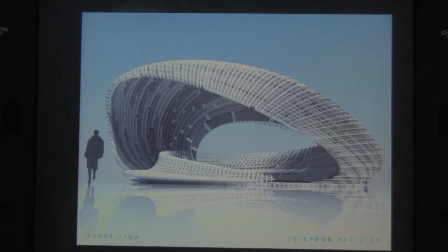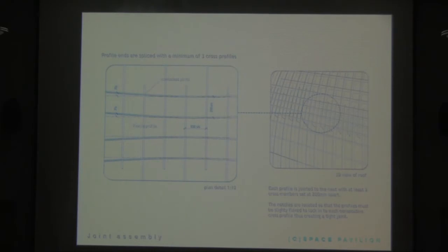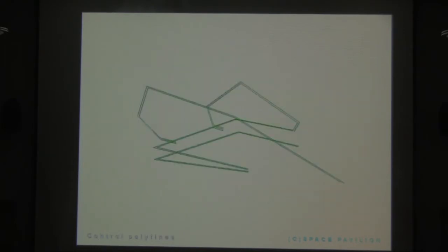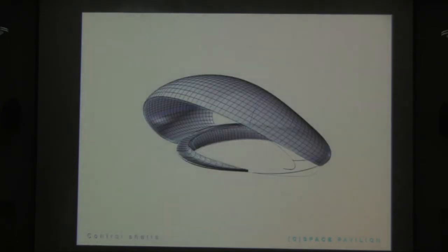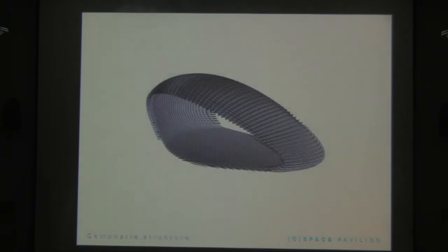So it's thin sheets of concrete with fiberglass filament mesh material, which basically makes it like a fiberglass or concrete plywood. Comes in 1.6 by 2.6 meter sheets with a 13 millimeter thickness. We proposed a basic notch joint flexed into position, overlapping notches, a modeling process which was driven by a series of polylines which define curves. Those curves define a skin. The skin gets sectioned in both directions. Those sections get intersected to produce a series of intersections to identify where those notches fit together.